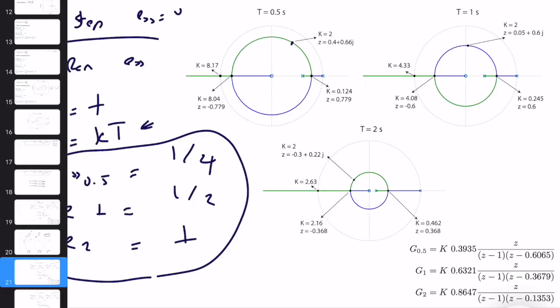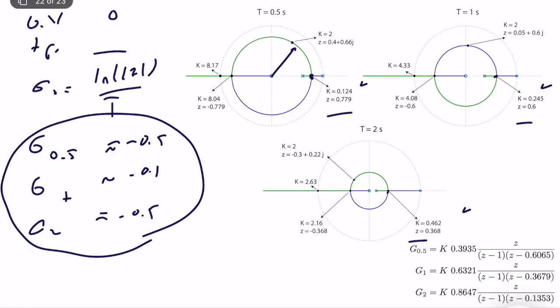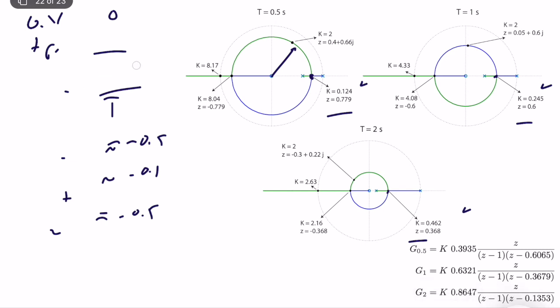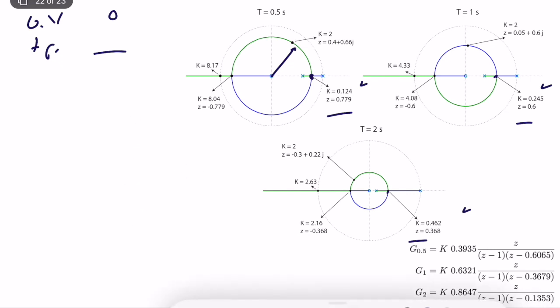Okay, that's good. So I think we are doing good, because when I was comparing these points, the points where response is critical damped, no overshoot, peak time is redundant, and settling time is same. It's not changing. So I'm not losing anything currently with respect to different root-locuses.